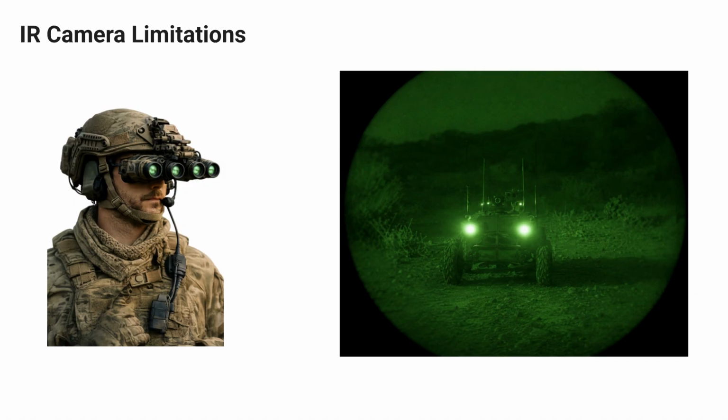While IR cameras are useful for night navigation, the military may have concerns about using them continuously in tactical environments. The main issue is the IR illuminator. Although its light is invisible to the naked eye, it can be detected by enemy night vision goggles, IR-sensitive cameras, and other electro-optical sensors. The main military concerns are, first, that the illuminator may reveal the presence of the unmanned ground vehicle. Second, it may expose the vehicle's approximate position and direction of movement. Third, the IR beam can indicate where the camera is looking, reducing the advantage of covert surveillance.